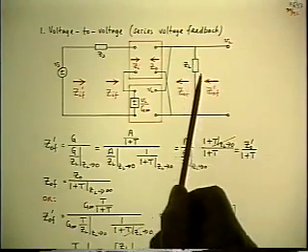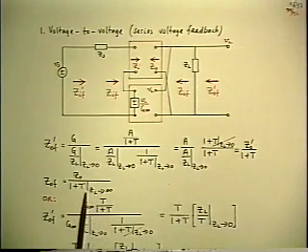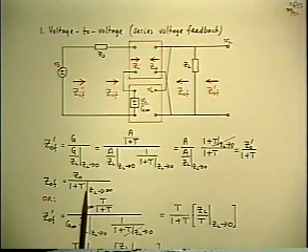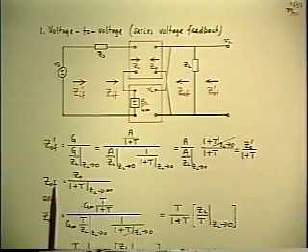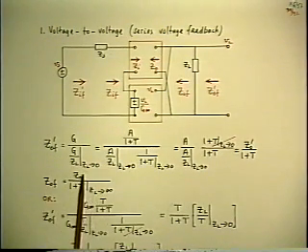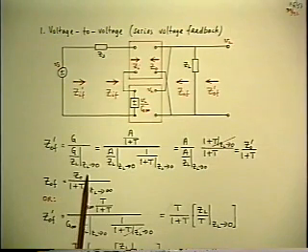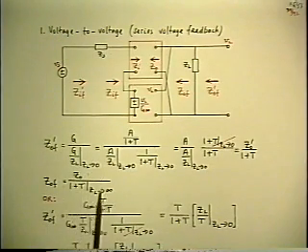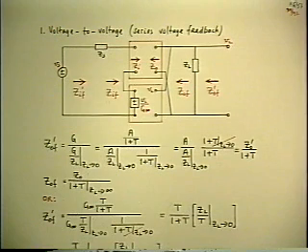But when you let ZL go to infinity, it gets bigger. Therefore, the T gets bigger if you take that limit. You can't say how much bigger, but bigger. So the conclusion is the inside output impedance with feedback is equal to the inside output impedance before feedback divided by a factor which is bigger than F. You get a bigger reduction factor. That's not such a well-known result.